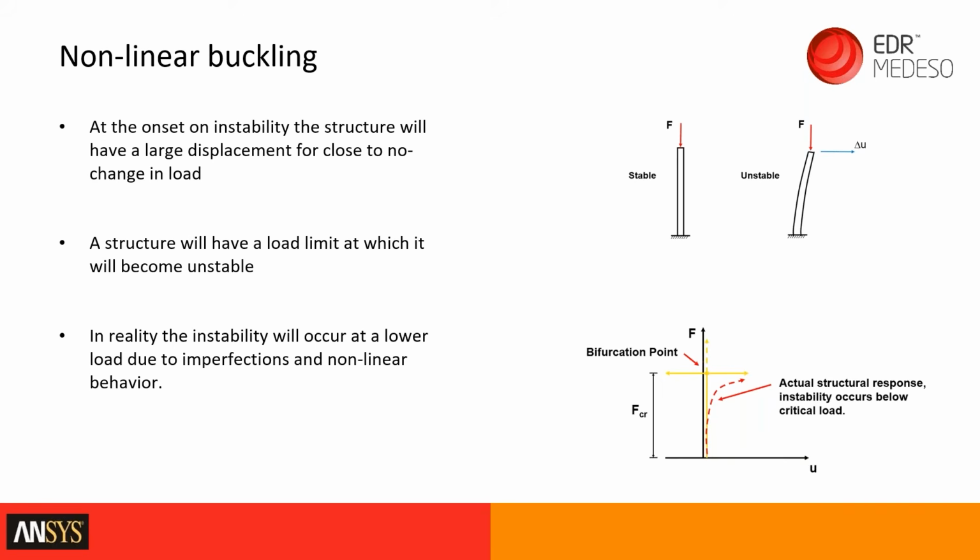Both these methods give a non-conservative result. The reason being is that in the modeling world, if you imagine taking a tube and applying a load vertically, as we can see on the right side, normally that tube is perfect. It's perfectly shaped, it has perfect geometry, there's no corrosion, there's no imperfections in the material model.